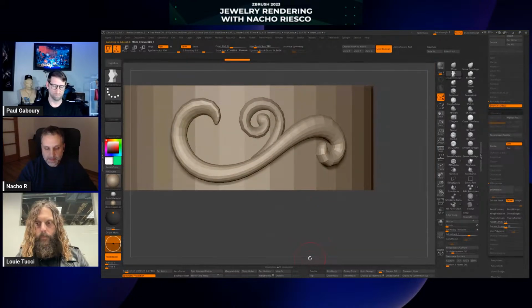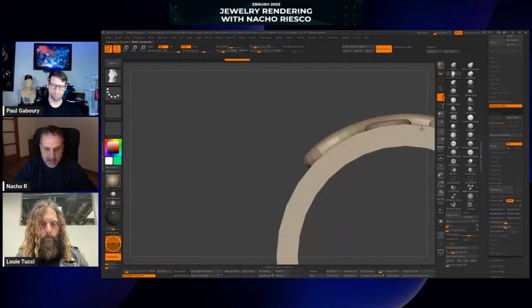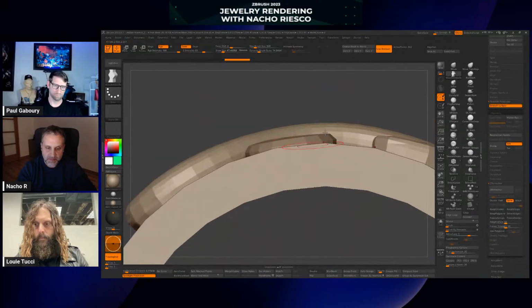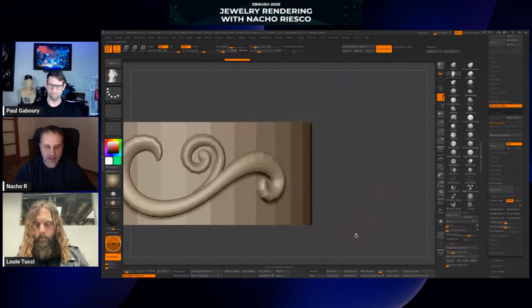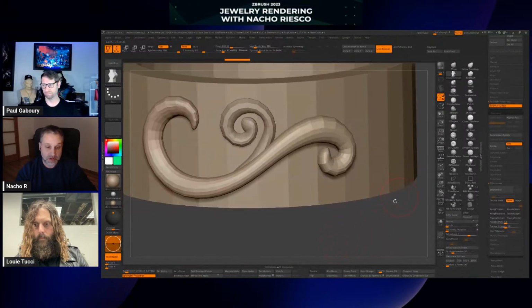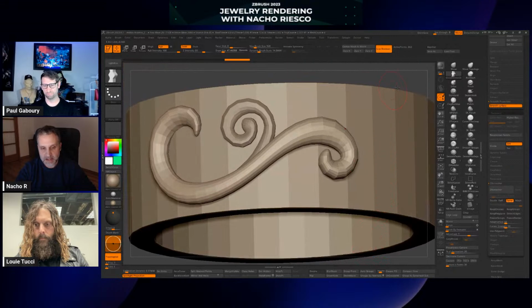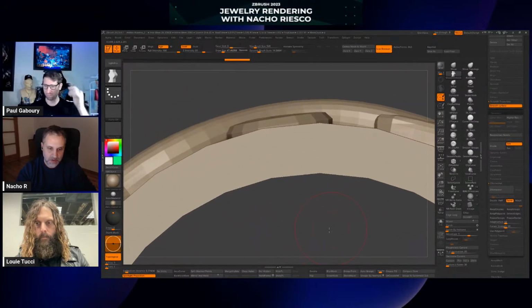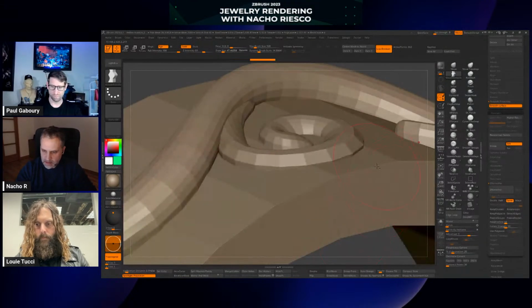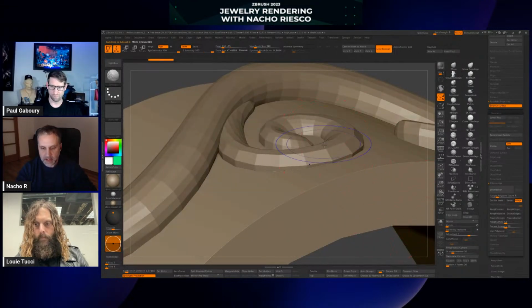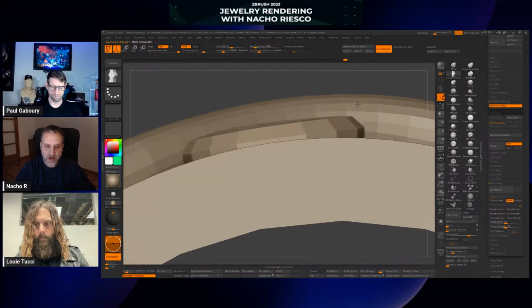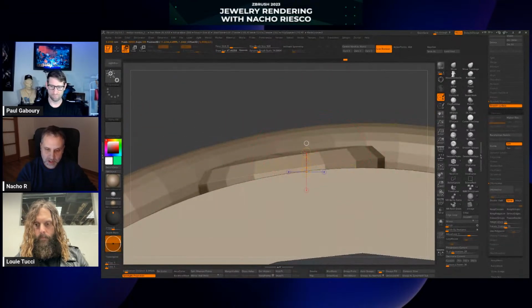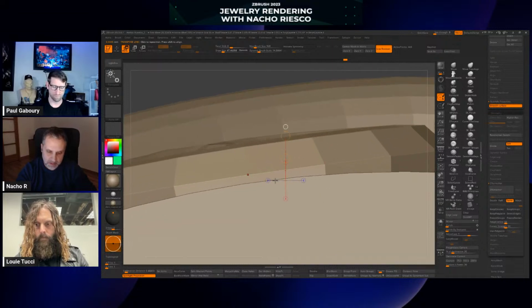And this is the same process during the sculpting process. As I said before, things could look nice on your screen, but you should be worried about the thicknesses. So during the sculpting process, you should be worried about the measurements. What I'm going to do is start checking the thickness we have here. Here we have 0.4 millimeter. Point to point, we can reach almost 0.5 millimeter.